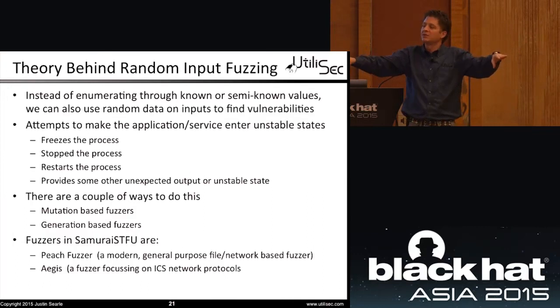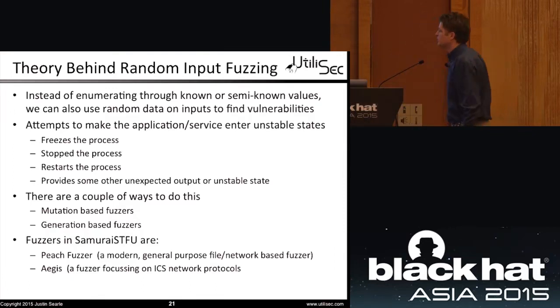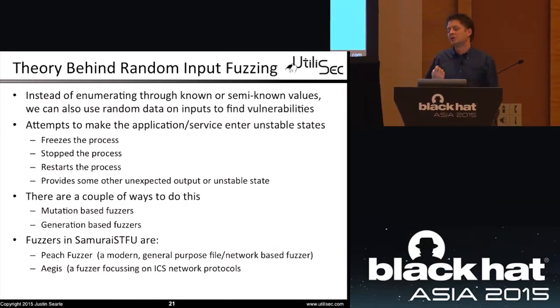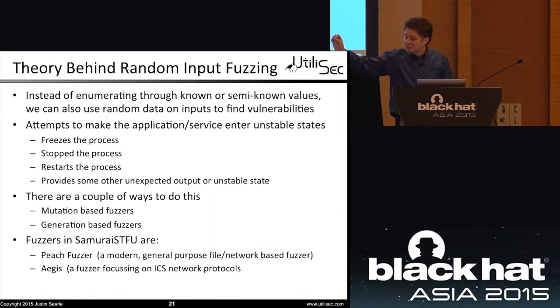So by finding a vulnerability and uploading some type of interpreter payload through Metasploit, we can gain control over that upper endpoint and have a presence on that server, even in something as simple as Modbus. Okay, so that's probably one of our biggest concerns when we talk about security: somebody not just getting their hands on a PLC, but getting their hands on a PLC, replacing it with their own tool, and then trying to attack the master servers from that network point.